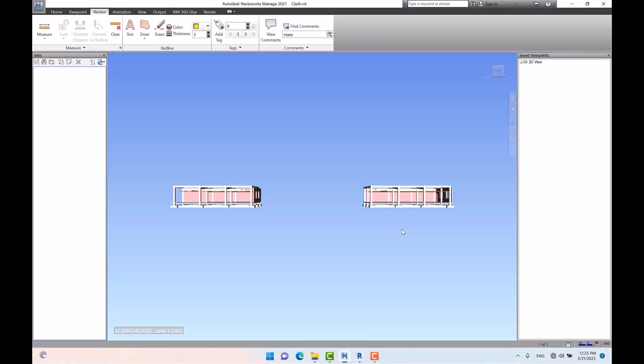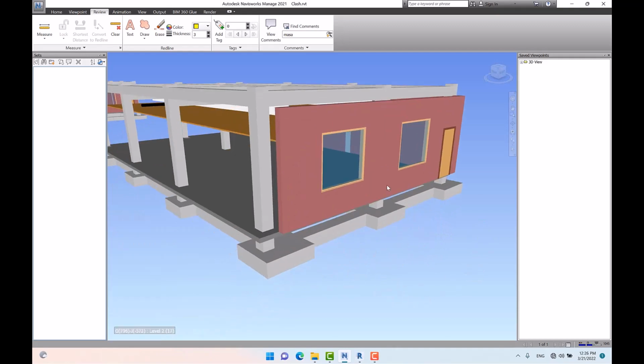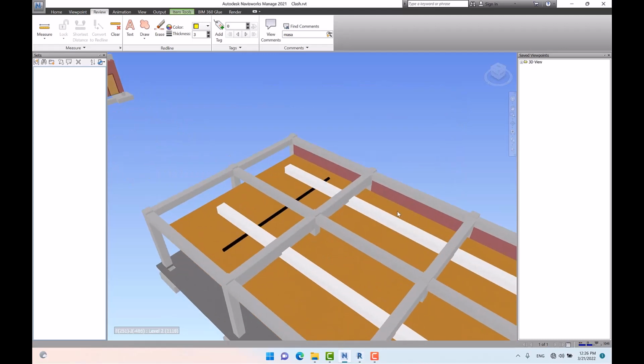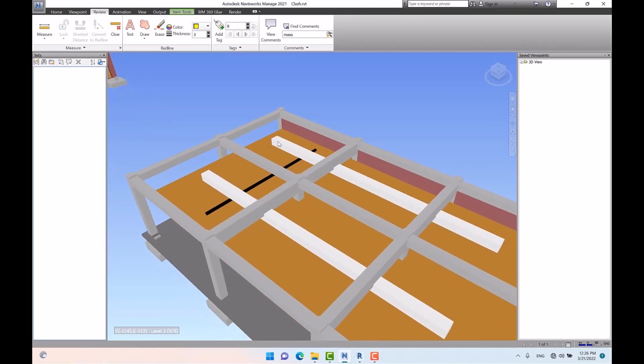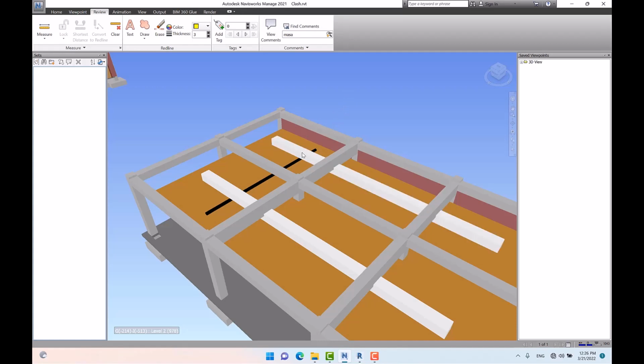To open the Revit file. Well done, the Revit file is prepared. For example, check this out. Here if I select this wall, as you can see here the conflict or clash is clear. If I select the duct, if I select them or hide them, as you can see we got duplicated ducts here, which shows the conflict here. Undo, again I select it, then I hide it. Look at here, select hide.